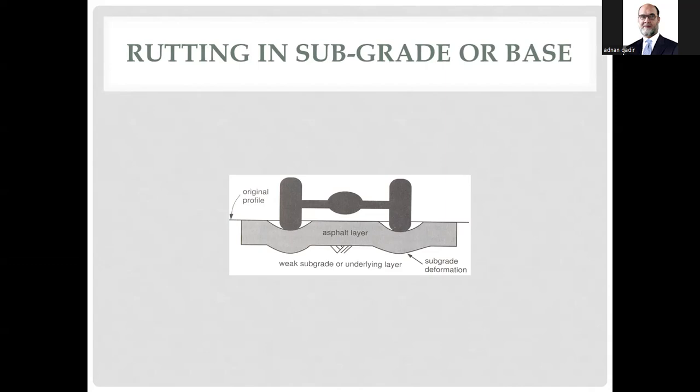They can catch the shortcomings in the selection of the pavement material, and sometimes in the design. Experienced people know that for this type of road, the asphalt wearing course cannot be less than 2 inch, and the asphaltic base course cannot be less than 4 inch, because this is a motorway or a very highly demanded road. It may not have such a small thickness.